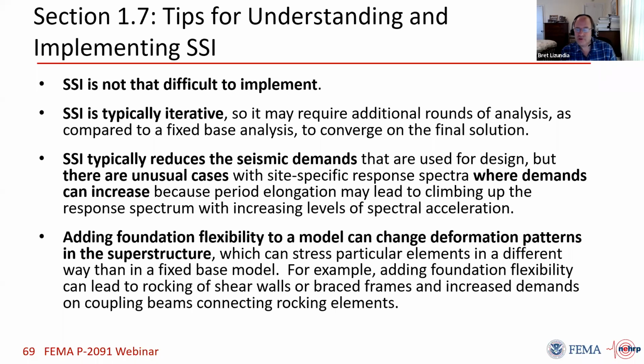It usually reduces seismic demands. There is that situation I showed you where you climb up the response spectrum and things can get a little longer, and then you can go up from near the plateau on the left, short period side of the response spectrum.